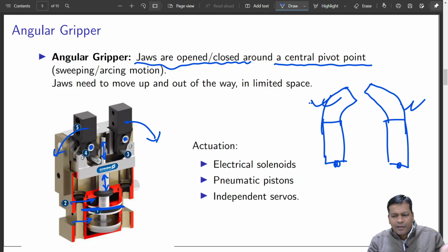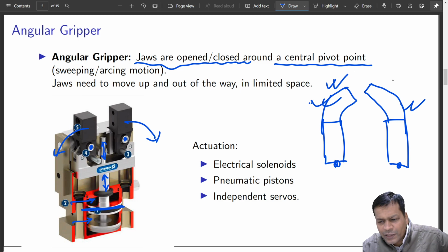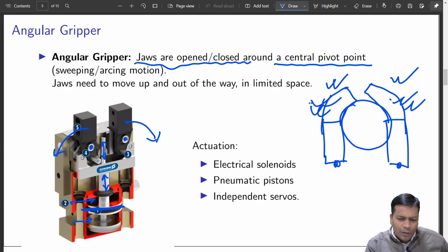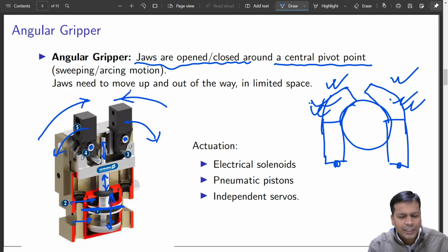Again, both the fingers will travel similarly, but you need an arrangement like this which makes it quite safe also. Yes, because it can envelop what is grasped. Even in case of parallel fingers, you can have this type of arrangement. There are various ways this can operate, but this is very quick because it is not linear motion. When this is moved in a straight line, the closing is not proportional. So as it goes closer, it becomes faster. So this is very fast in operation.